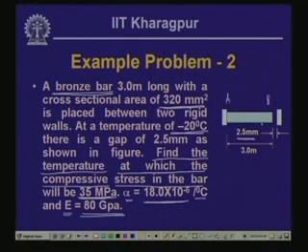First we allow it to move freely, thereby there will be deformation because of the change in the temperature, and now we impose some external force to bring back that deformation to its original position, thereby how much force we need to put to bring back the member to its initial form. We evaluate that, and if we compare these two, from these we can arrive at an expression which we generally call the compatibility equation. So, that is what we need to do in this particular case.